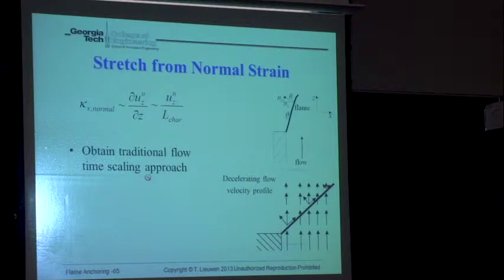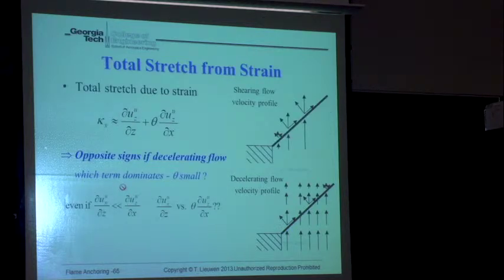But what you see then is, if we go back to this equation, this term scales as u_z on L, where L would be an overall jet diameter, let's say, plus a term that scales as S_D, flame speed, divided by a shear layer thickness. So these two terms, again, trying to add them, life becomes pretty complicated, pretty interesting pretty quickly.